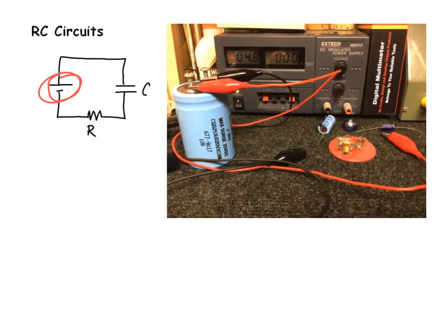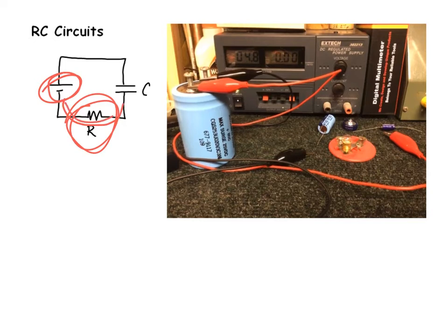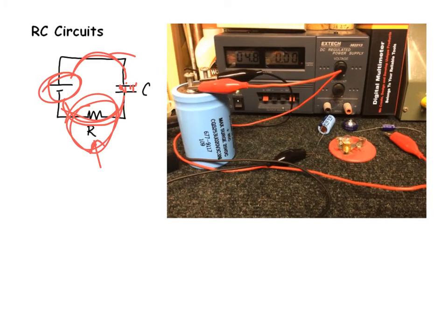So how long did it take to charge the capacitor? Well, that will depend on the resistance. If there's a lot of resistance, then it's going to take a while for the electrons to flow around the circuit and bring this thing up to charge, and then there's a field in between the two plates, like that. If I have a bigger resistance, it will take a longer amount of time. If I have no resistance, it will be almost instantaneous. So the wires we think of as having almost zero resistance. So almost in an instant, it charged up the capacitor.